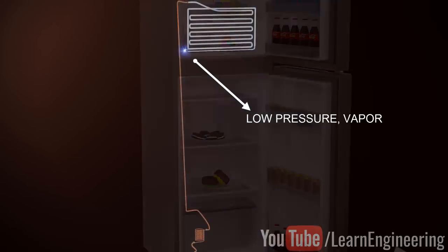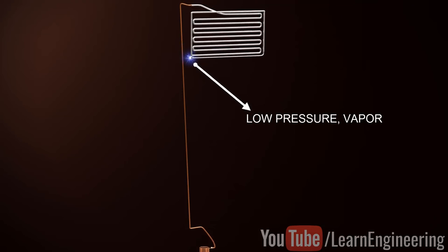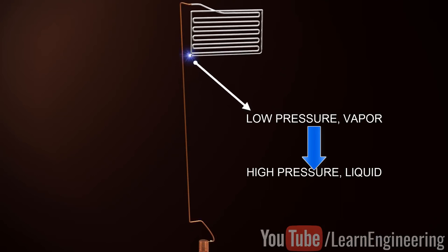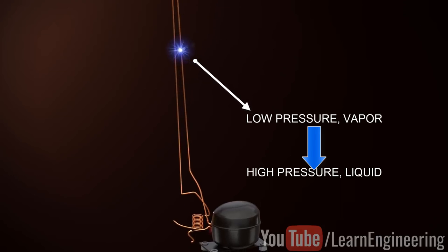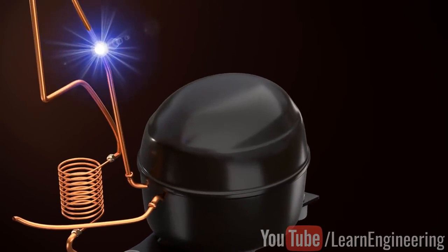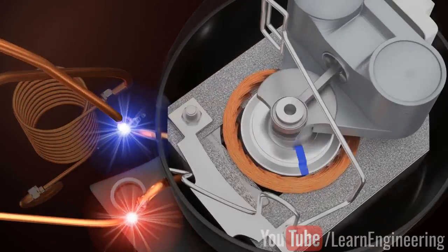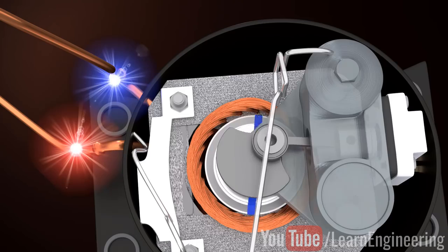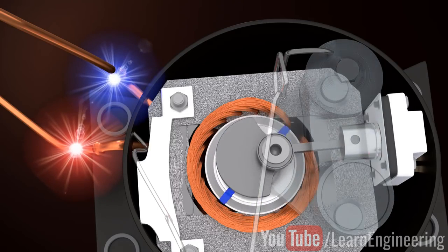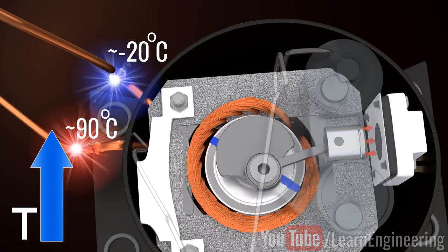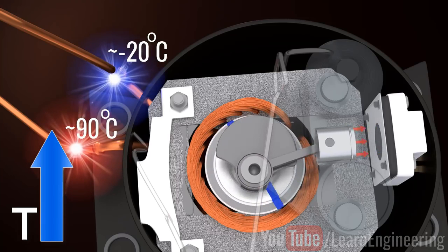If we can take this low-pressure refrigerant to the state before throttling, that is high-pressure liquid, we will be able to repeat this process. So, the first step is to raise the pressure. A compressor is used for this purpose. The compressor will raise the pressure back to its initial value. You can see that a reciprocating type compressor is used here. However, since it is compressing gas along with pressure, the temperature will also increase. This is unavoidable. Now the refrigerant is high pressure vapor.